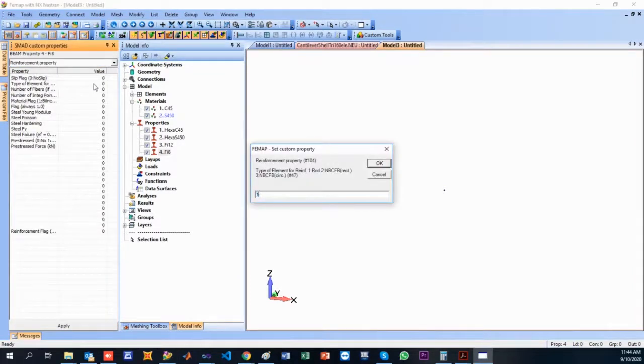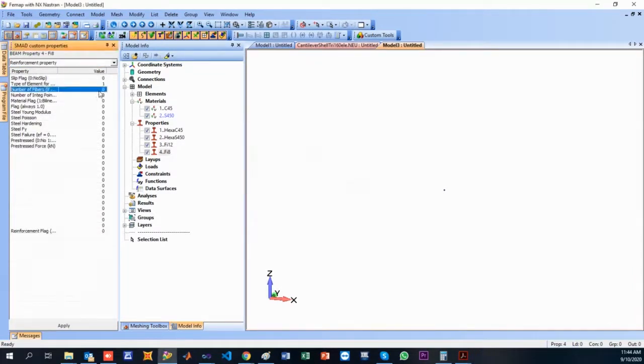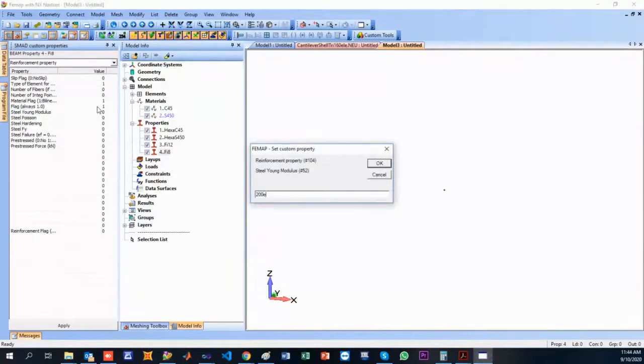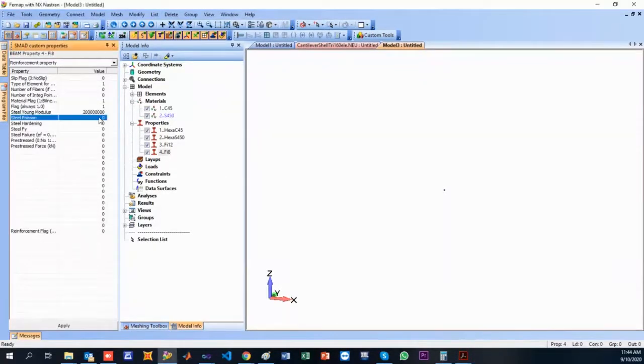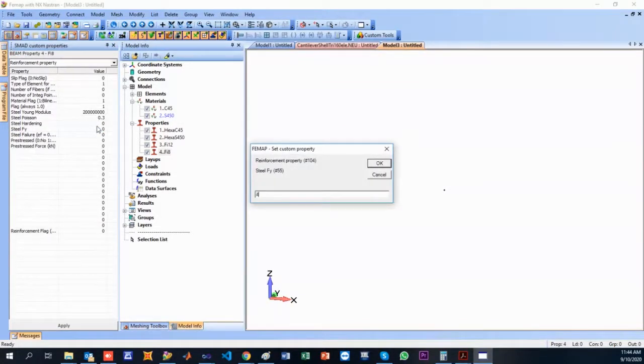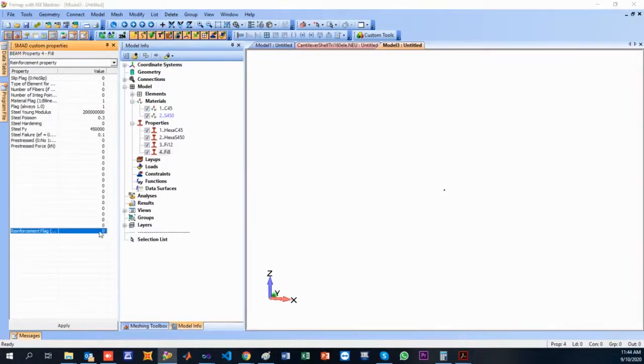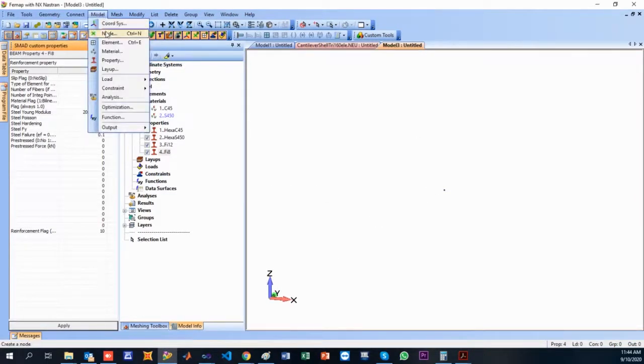Okay, type of element here I will use rod element, and no fibers are needed. Bilinear should always be 1. Young modulus the same as before. Poisson ratio, no hardening, yielding. Okay, and of course our failure point 10%, and this is always 10. I'm done. So let's start drawing here our nodes.